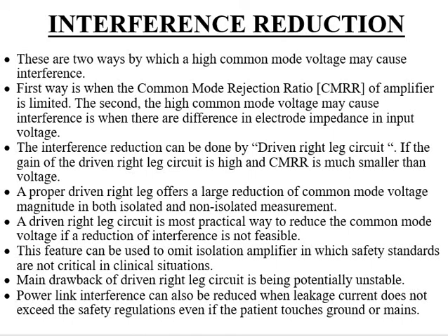If you search for a solution for each and every individual problem, then it leads to complications. So what we can do is segregate the source. The source for all the problems is the common mode voltage, the high common mode voltage. How can this be reduced?